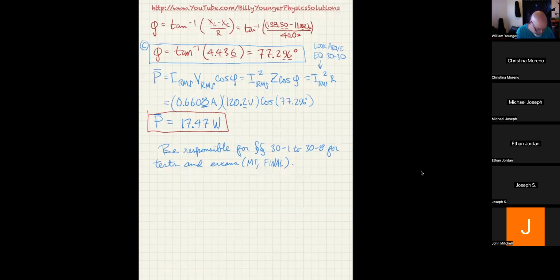Your author does a good job telling about what you can do. So for instance, we see that really high frequency stuff can't make it through an inductor. So if you want to, for instance, connect a stereo output, the actual sound output from a stereo, to a woofer, that's supposed to be all low frequency stuff. You could put a solenoid, which is basically an inductor, in line on the wire between the stereo and the woofer, and that would stop all the highest frequency stuff getting in, and your woofer would play just the lower frequency stuff, which is what a woofer is supposed to do.